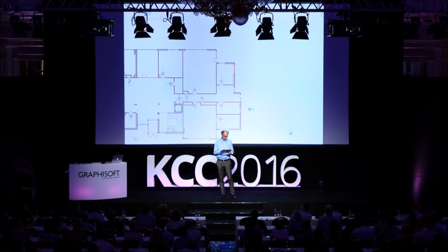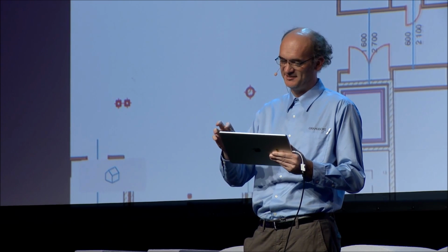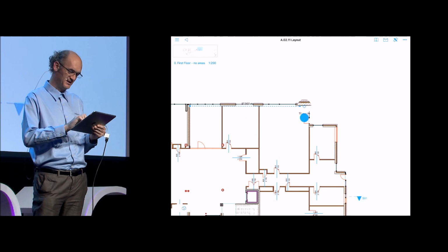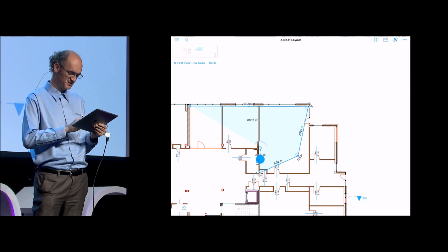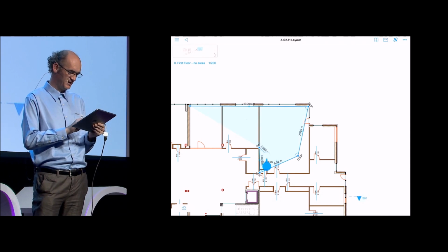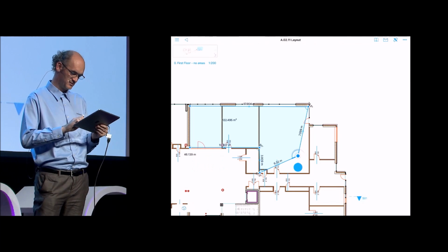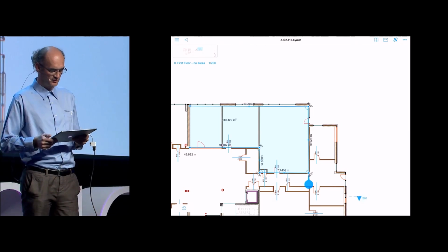I guess you mean BIMx by clapping. Okay, so measuring tool, top right corner, I tap it, I get a nice cursor. I can position it to the corners of the room. I also get a small magnifying glass showing me the exact location. And I also get, oops, a mistake there, but don't worry. So I also get the numbers as live feedback on the screen, the side, the edge length, and also the combined surface. So this is it. Last corner, 140 square meters.